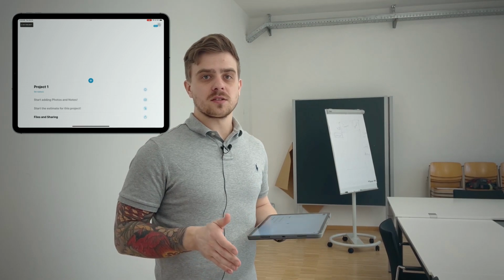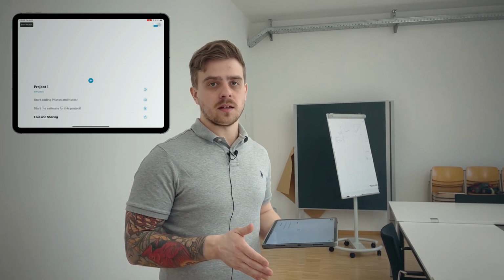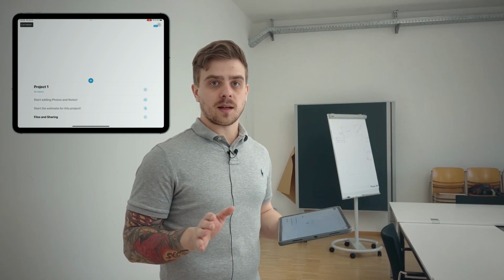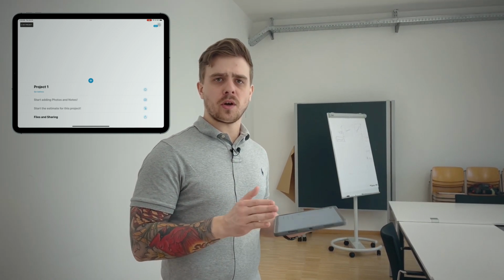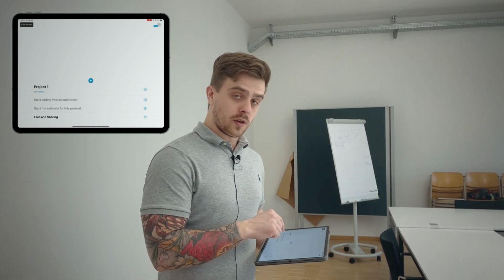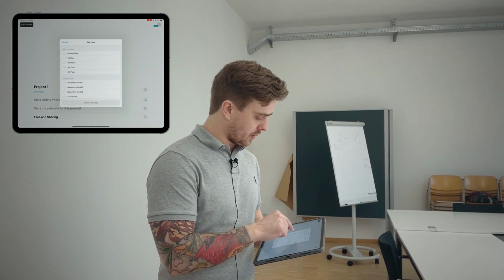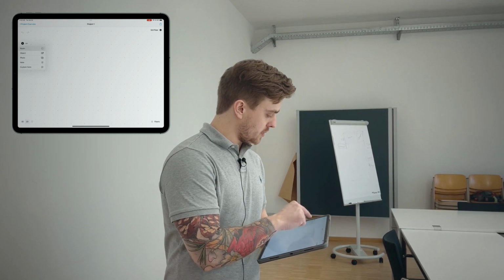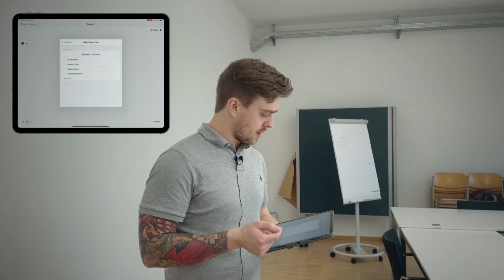So first things first, we actually have to create a floor plan in magicplan. So I've got my iPad here, we're in our office, and I'm going to scan in using LiDAR and show you how that works, as well as the object detection and how we can make some corrections with a Bluetooth laser after the fact. So I've created a new project. We're on the 3rd floor. And I'm going to go ahead and add a room using the scan with camera option. We're in a conference room right now.